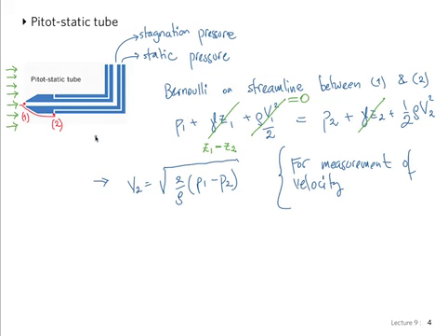Yeah, we call it the static pressure, but basically the name only applies to the actual thermodynamic pressure, the P that appears on all our equations. We just call it static pressure to differentiate it from dynamic. Dynamic pressure is the one that only comes from velocity, the velocity term. So it's just the language that was chosen historically. I can't really explain it.